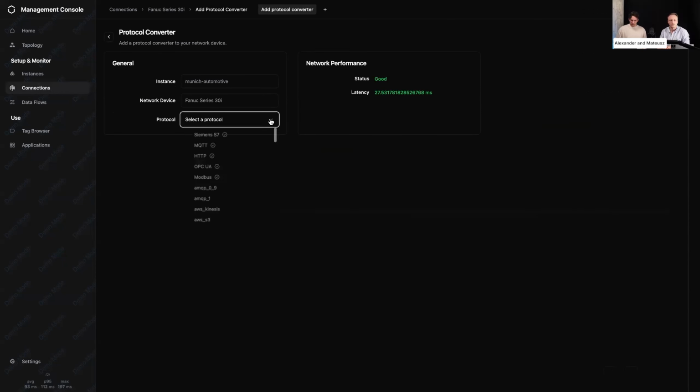Once you have that, a subject matter expert can very easily access this connection, contextualize the data, and read out the data points. For this, we have tons of templates, some native for S7, MQTT, OPC UA, Modbus, and so on, and many of the classic IT interfaces you can imagine. So to also enable you to connect, for example, over SOAP to SAP or any other, pardon me, CMMS system, for example.